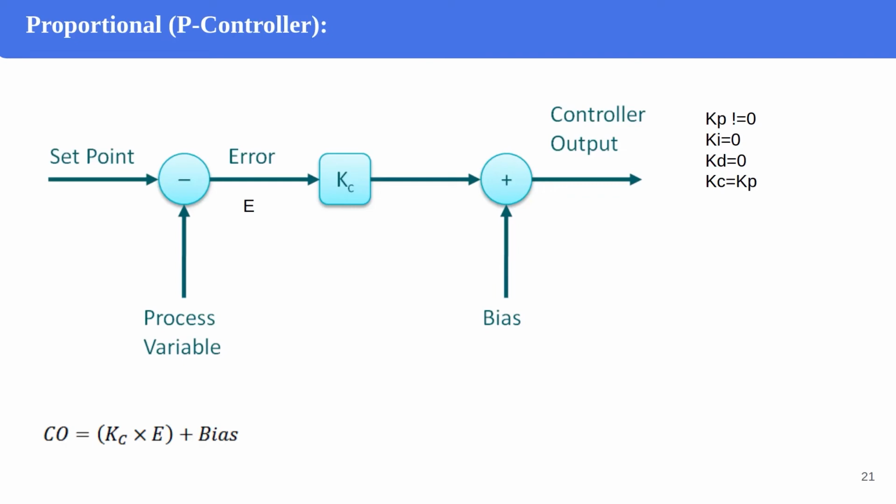For industrial processes, most of them are nonlinear, so we need to convert this nonlinear system to a linear one and do linearization, because a PID controller just works with linear systems. To do so, a signal bias is needed to add to our equation here.